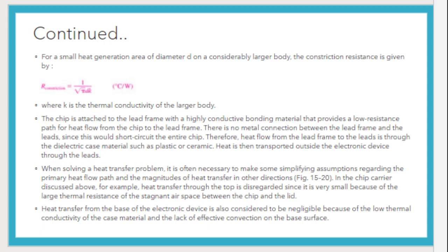There is no metal connection between the lead frame and the leads since this would short circuit the entire chip. Therefore, heat flow from the lead frame to the lead is through the dielectric case material such as plastic or ceramic. Heat is then transported outside the electronic device through the leads.